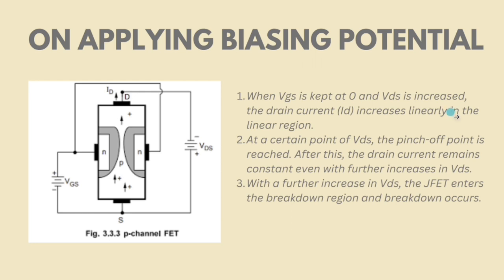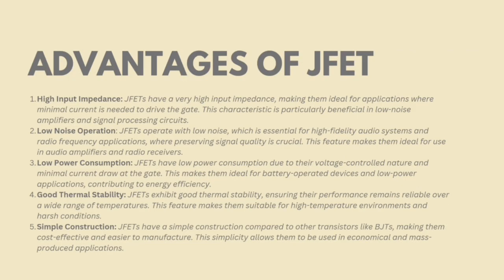So here we conclude the working of the JFET, and let us now move on to the advantages of the JFET. There are different advantages of JFET which make it optimal to use and an industry standard. Some of the advantages include high input impedance, low noise operation, low power consumption, good thermal stability, and simple construction.